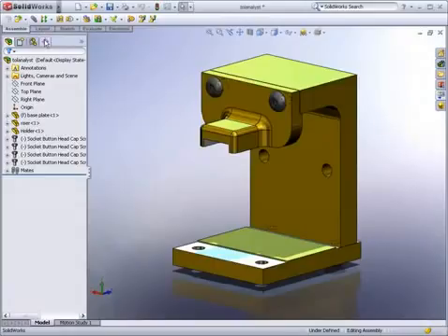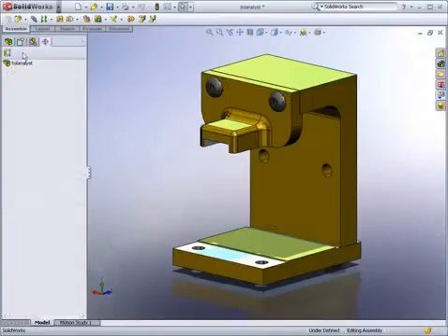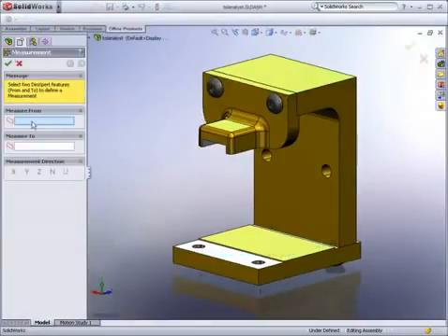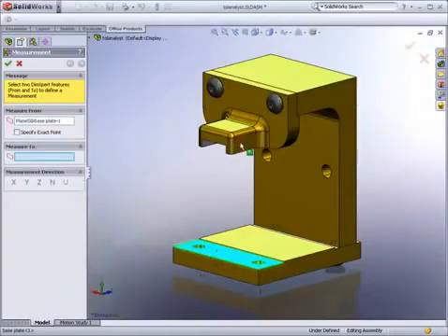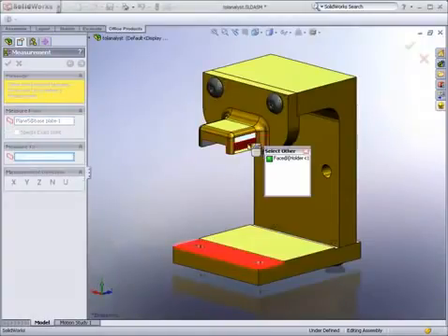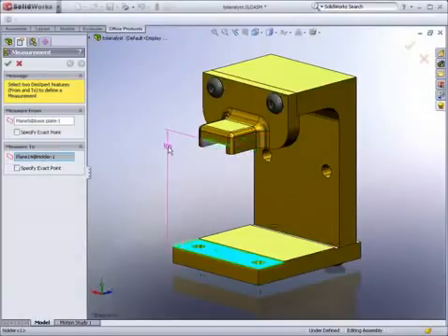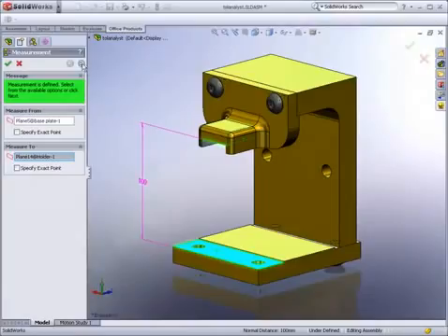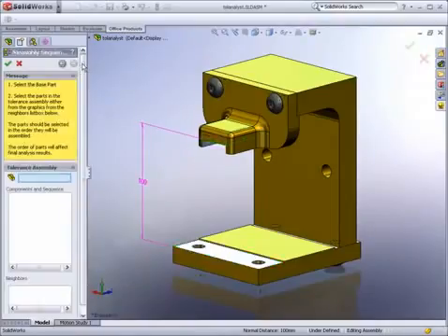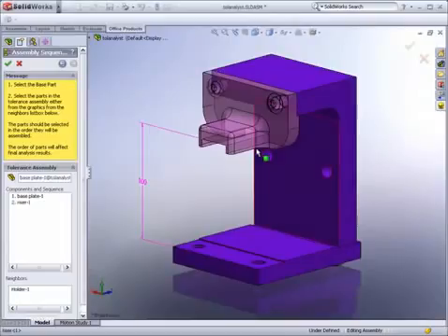To begin the analysis, we select the DimExpert Manager tab of the Feature Manager and select TolAnalyst Study. This process requires 4 simple steps. First, we create the measurement between the face on the bottom plate and the face of the slot on the holder part and place the dimension. Using the arrow keys in the TolAnalyst wizard to move to the next step, assembly sequence, we have to indicate which parts are involved in the assembly between the bottom plate and the holder part, selecting them in order.